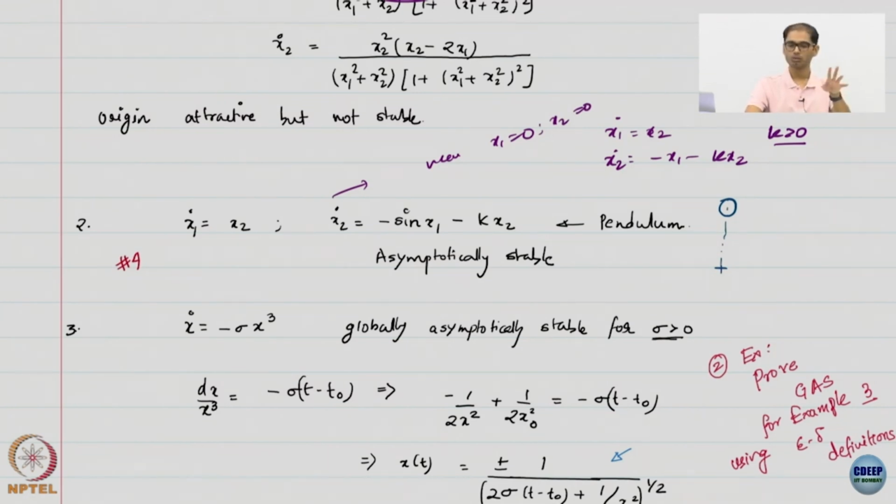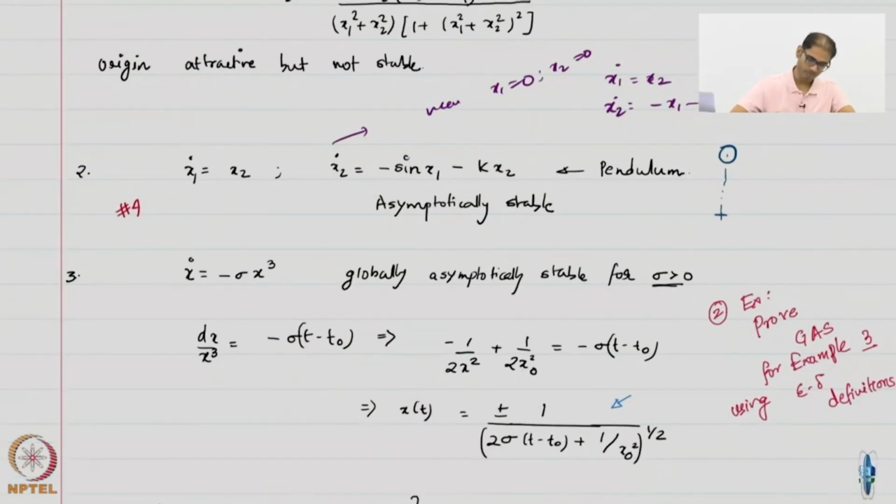Alright, makes sense. What most people do is they say that okay, you have these equilibria, but it is an unstable equilibrium, therefore in reality you will never actually stay here, which is true. If you take a pendulum, even if you start here, you will never stay here. However much your damping is, even if it is slightly off from this, which it will be in the real world, you will go back to the (0, 0) equilibrium, but it is not global, sadly. So, remember that, not a global property.